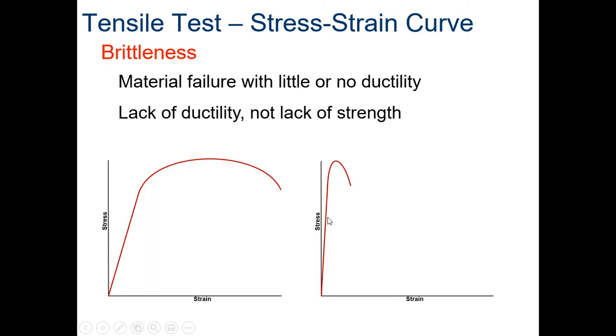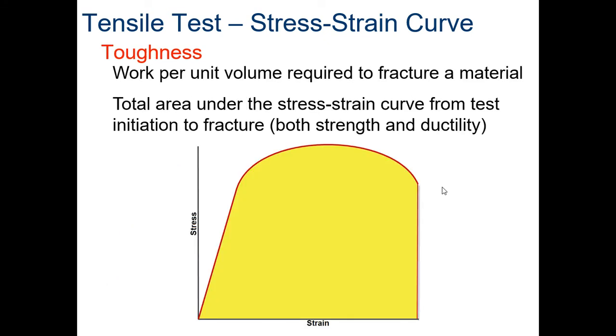Now, what do we look at here? Well, they both have the same maximum amount. Both have the same tensile strength, but the one on the right is a lot more brittle. It doesn't have as much strain. So you've got different types of metals that will do that. Brass, stainless steel. That first video was stainless steel, so it was actually necking pretty good. The second one was made of iron. It had no neck. It almost broke right away. So different materials have different properties.